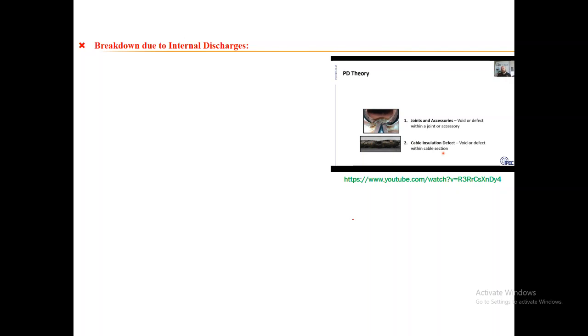You do get PD in the pure insulation. It can happen. It's much less common with XLPE, like I say, but if you're looking at oil and paper cables, the older cable types, we still have a lot of that in the United Kingdom, for example, you can find a lot of PD occurring in the oil and paper. However, it's not necessarily always a concern, and I'll come on a little bit about that later.